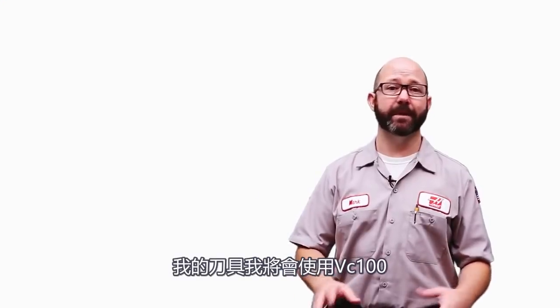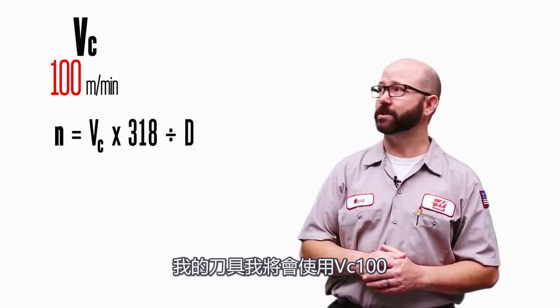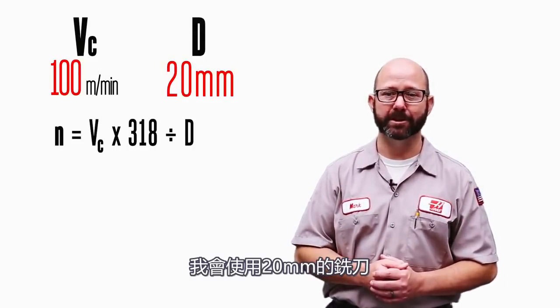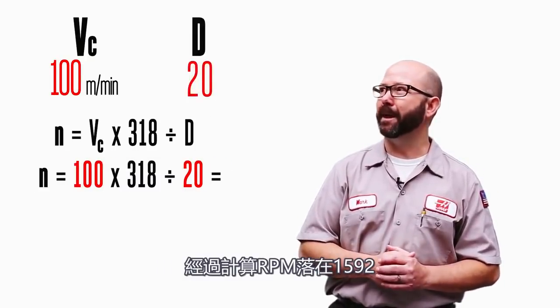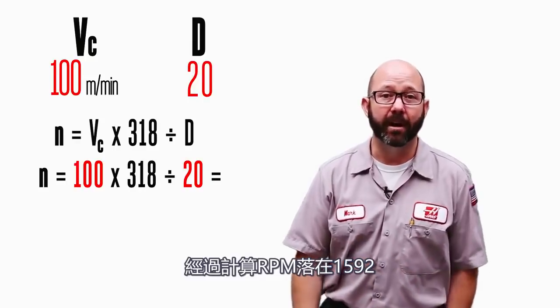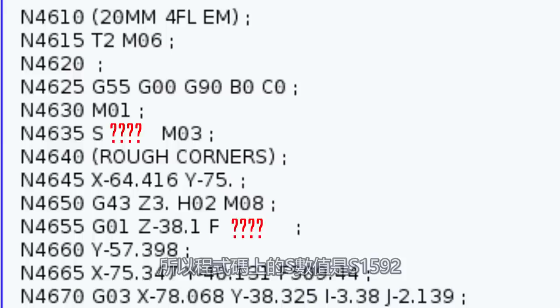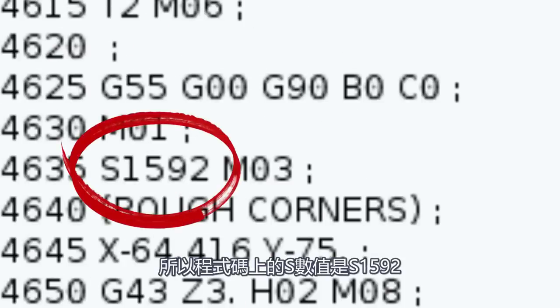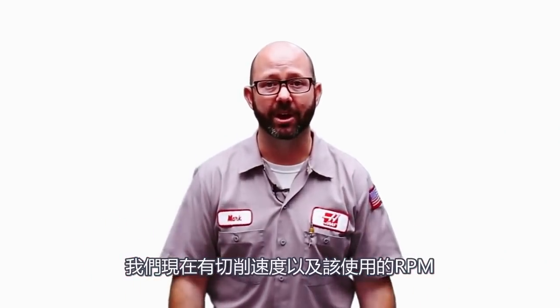For my tool and material, we're going to use a cutting speed of 100. That's 100 meters per minute. I'm using a 20 millimeter end mill, so we'll drop in 20 there. And after a little bit of math, we come up with an RPM value of 1,592. So our S code back in our program is going to be S1592. We now have a cutting speed, an RPM value that we can use with our tool.